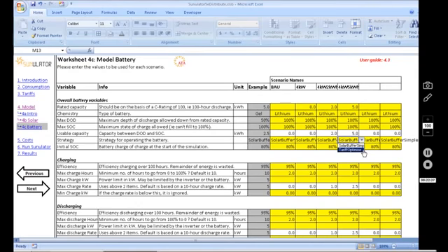So with the Tariff Optimized, it actually makes a simple forecast of how much generation it's expecting that day. It just assumes it's going to generate the same as yesterday, and a forecast of how much consumption you're going to have through the day. It assumes the same as one week prior, and it does a pre-simulation to work out how full the battery is going to get through the day, and has it got some extra room in there to store some electricity by pre-charging from the grid, and would that be helpful later on in the day?